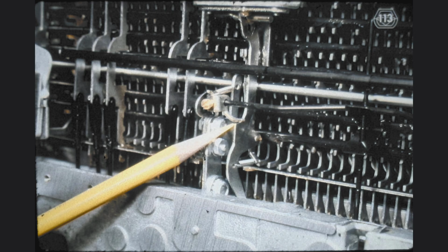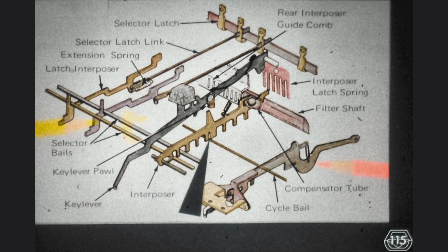When a shift operation is in progress, the indicated front-to-rear clearance between the character interrupter lug and the indicated step on the cycle clutch latch link should be maximum without allowing the engagement of the cycle clutch when the movement of the link is stopped by the character interrupter lug. The front-to-rear position of the character interrupter is controlled by the bracket indicated by the yellow pencil.